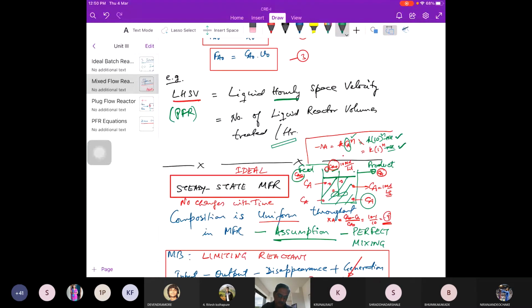ओके सर. यहाँ पर CA नॉट है, यहाँ पर ऑलवेज CA है. हाँ. यहाँ पर सब जगह CA है. दैट मीन्स यहाँ अगर मैंने 10 मोल्स पर लीटर लिया और अगर 90% कन्वर्जन है, तो the moment it hits this thing it becomes 1 mole per liter, because the flow rate is always very less compared to the volume of the reactor. And that is why the rate of reaction is low in CSTR compared to PFR for the same exit concentration. Okay, sir.